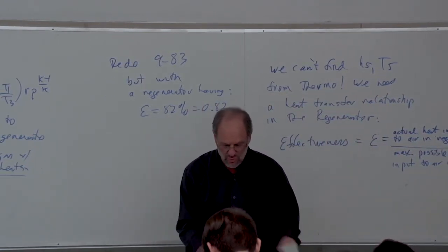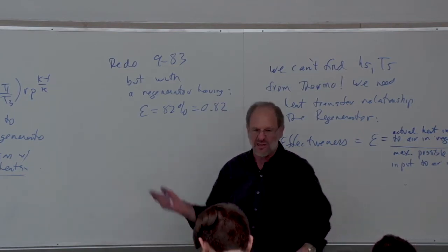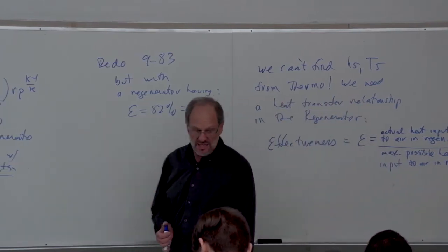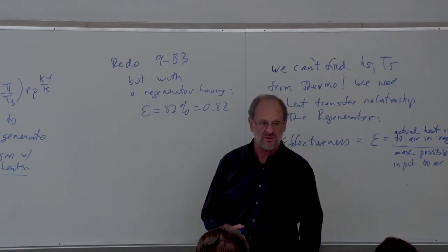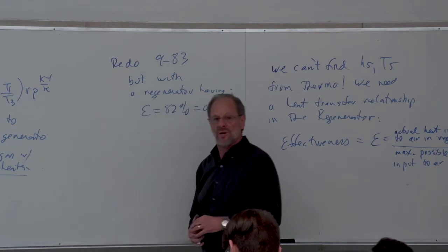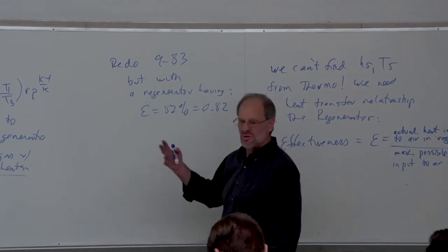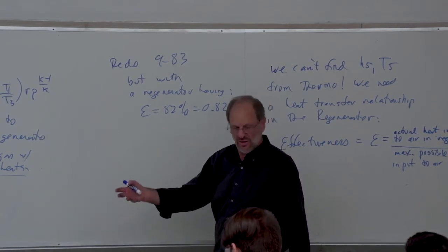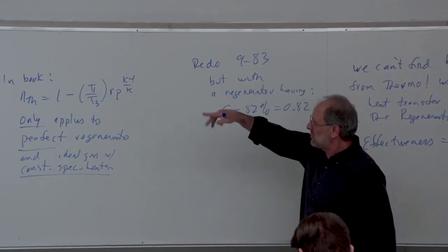So if we go back to that previous example problem, I'm not going to bother to put it back on the board. The first thing I want to note is that 95% of the problem is identical to the one we already did, right? We're still going to go from 0.1 to 0.2s. We're still going to use the efficiency of the compressor to go from 2s to 2a.